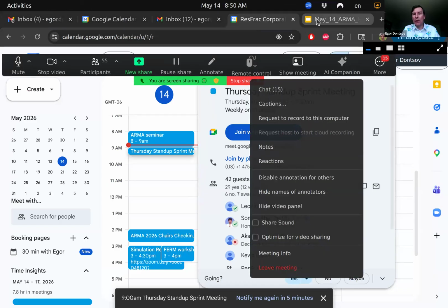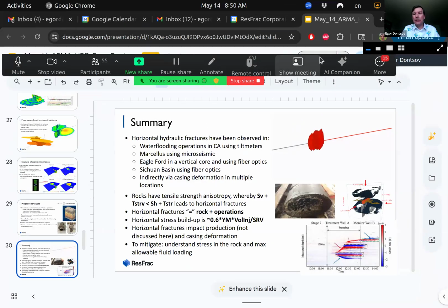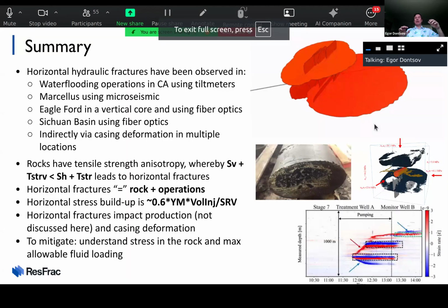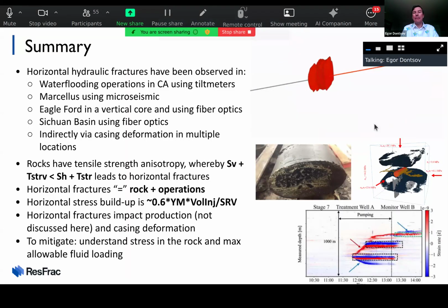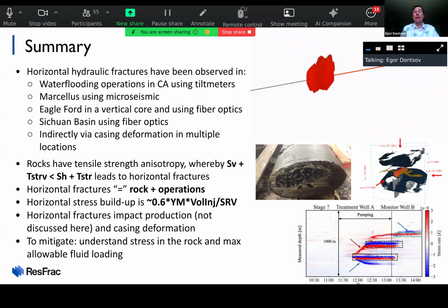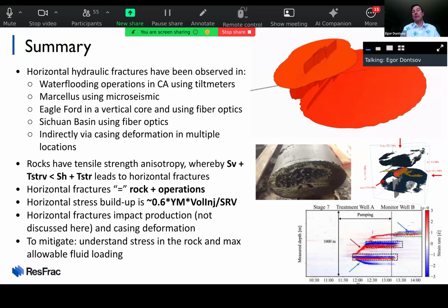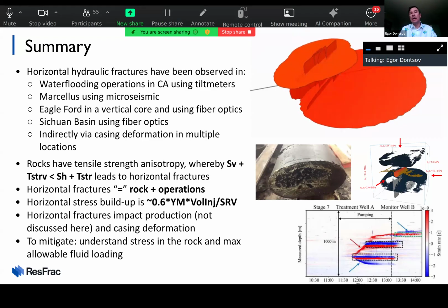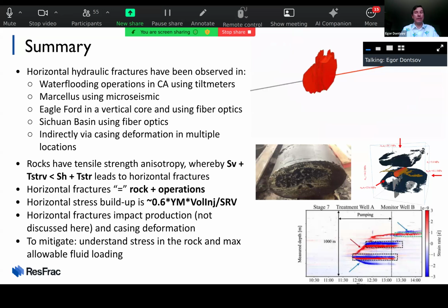Oh, another thing to keep in mind is something that we don't have right now in simulations, but in reality we have: anisotropy in elastic properties, right? Typically the vertical Young's modulus, which horizontal fractures feel, is lower, maybe by 3, 4, or 5 times.